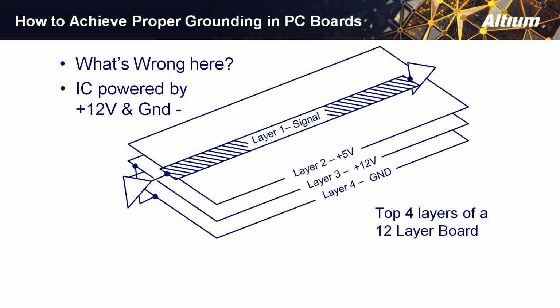And he said, what do you mean there's the problem? I explained to him some of the things we just went over about where energy travels in circuit boards. After doing that, I said, where's the energy going to travel in this circuit? With a trace on layer 1, in what dielectric space will the energy be? He looked at me and said, between layers 1 and 2. And I said, exactly. If the energy travels in the dielectric space between layers 1 and 2, where's the return current going to be? He said, I'd like for it to be in ground. And I said, but you know it won't be, don't you? And he said, yeah, the return current's going to be in the 5-volt plane.